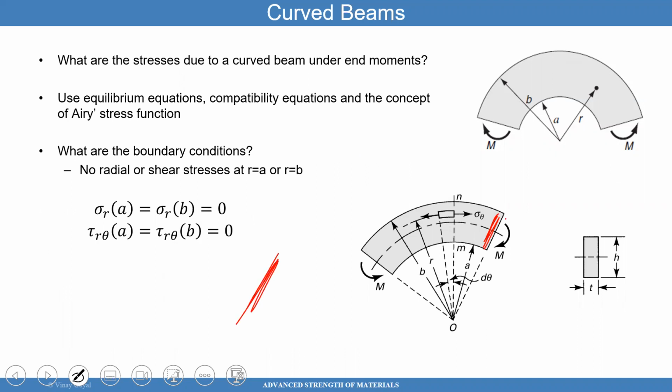I'm drawing that line here, as you can see. Hopefully that's clear there. And then that's the centroid of that. And I want to take moments about here, right? So say I have this sigma theta theta, and that's at a radius r, right? And I have to do an incremental value of dr, right?